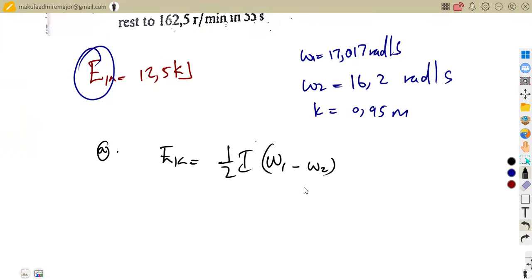So if you check here, we have this in rad per second, which is fine, but this one is the one that carries the mass. This is half of m k squared. Remember that. This is our formula here. So truly I can calculate the mass. I can remove the halves by multiplying by 2 here.